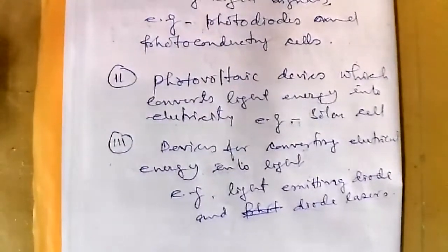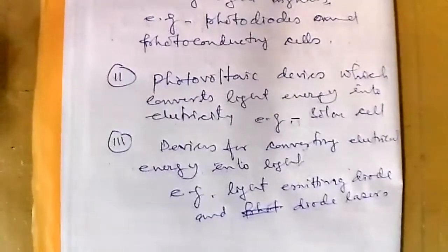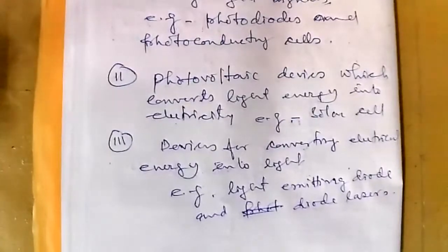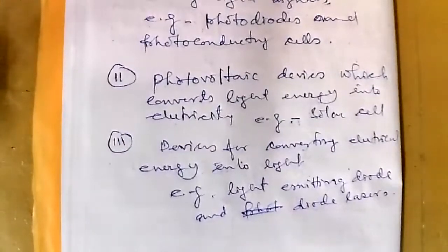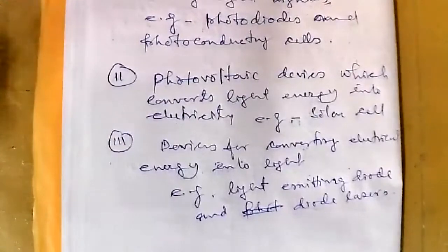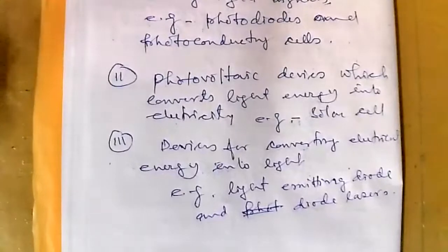See, from the figure, when the positive terminal of the battery is connected to point A, then the upper diode, which is connected with 10 ohm, will become active, and the lower diode, which is connected with 20 ohm, will become inactive.